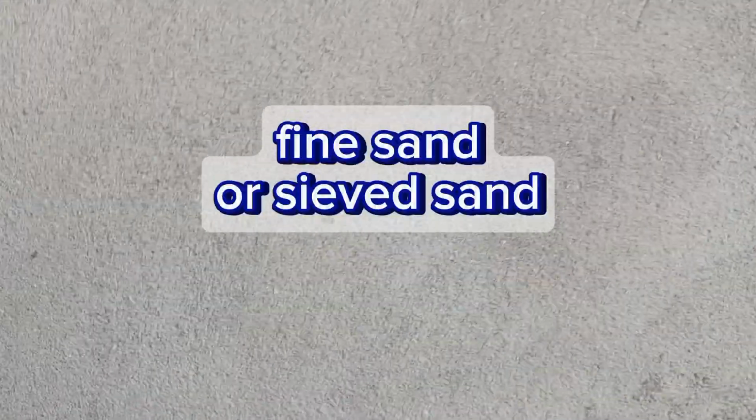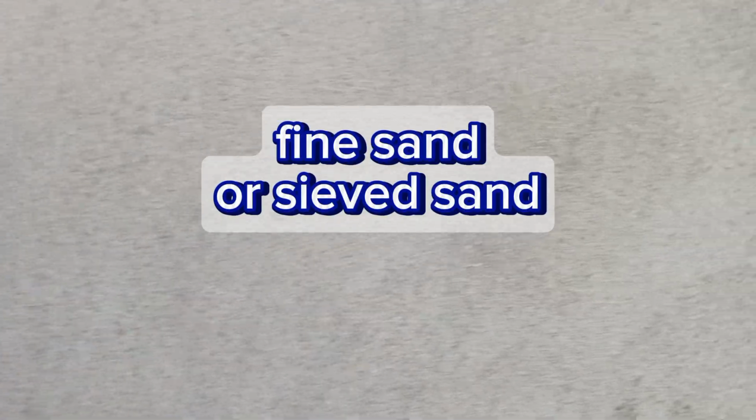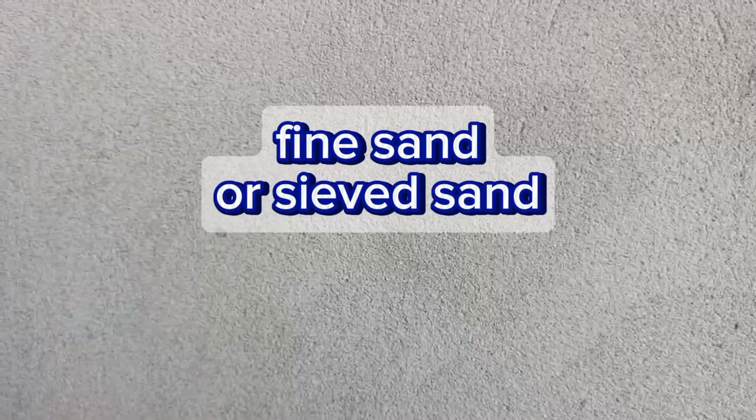So that sand should be a fine sand. If your sand is fine, then you are guaranteed that you are going to get an even wall plaster. So that is one thing to remember. The sand should be sieved on site to make sure that you have a fine sand to do your plaster works.